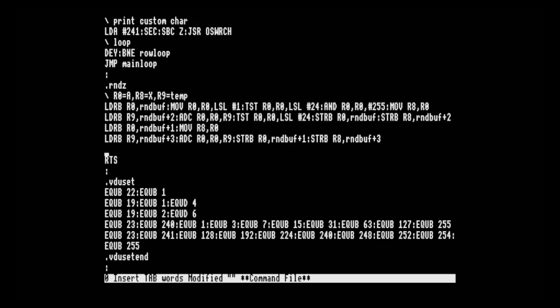On the ARM instead, what happens is the return address gets stored in register R14, known as the link register, and all you need to do when you return is you just move that address in R14 back to R15, which is the program counter. So effectively you do this, so move the link register in R14 into the program counter in R15, but you can use two little shorthands for these registers because they get used that way, so you can just say move the link register into the program counter.